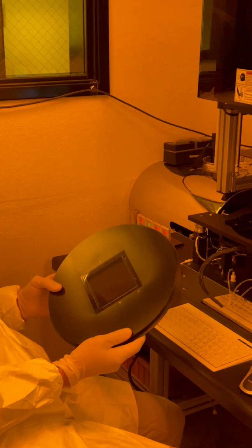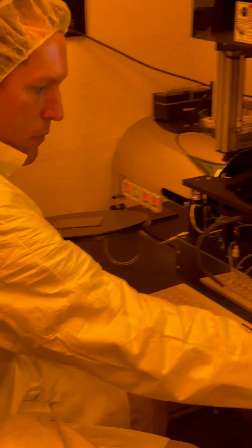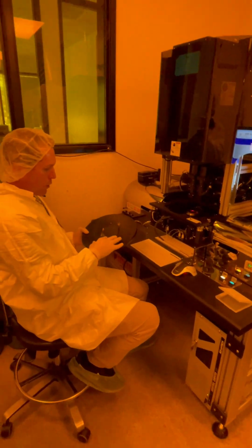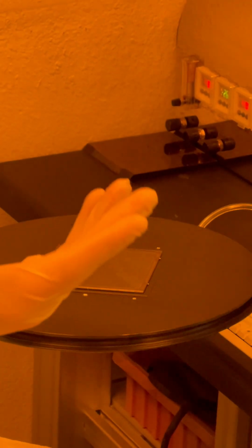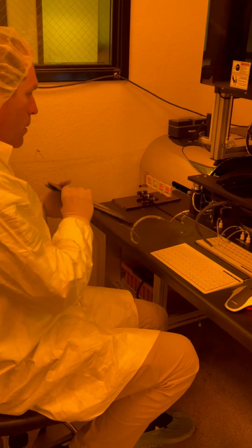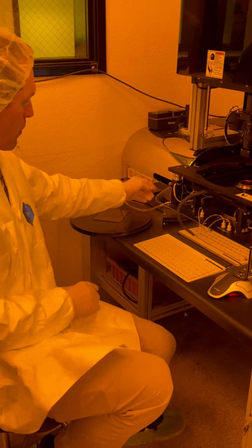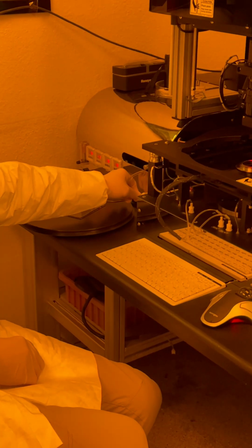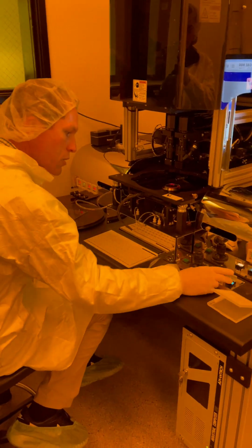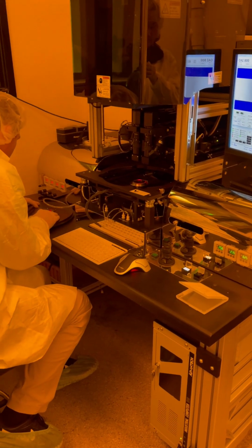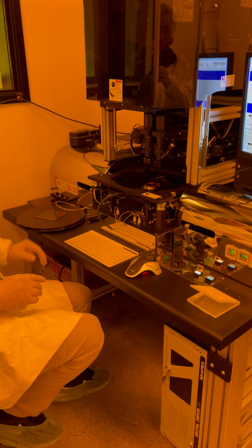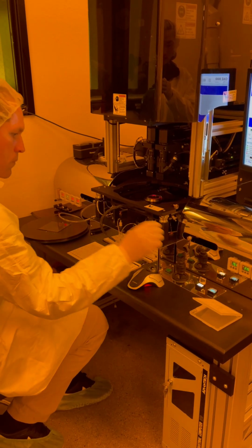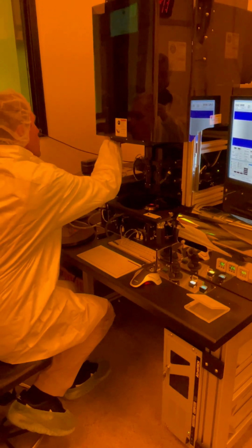So that's the mask holder, and your mask is just held in by vacuum. Vacuum button is right here. And there are mechanical clamps here to hold the mask in place in case of loss of vacuum, right? And when you switch mask holders, it's just a quick disconnect. I'll remove the mask now. And then to change the chuck, actually let me put this in so we can see what's going on.